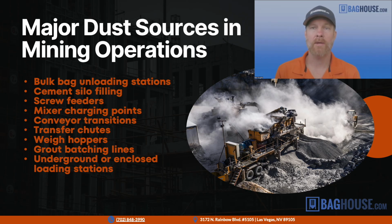In this case, a lot of the special attention goes into the hood design and the ducting design. If we're talking about ambient temperature dust, the dust collection system itself we size based on our standard sizing guidelines, but the make or break decisions come down to the capture point. Transfer chutes and conveyor transitions are especially important because poor enclosure or bad airflow through those can really just let dust spread throughout your facility. So let's keep that in mind.